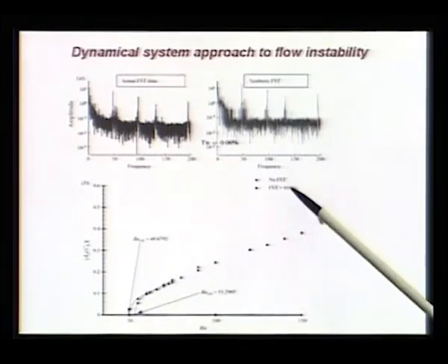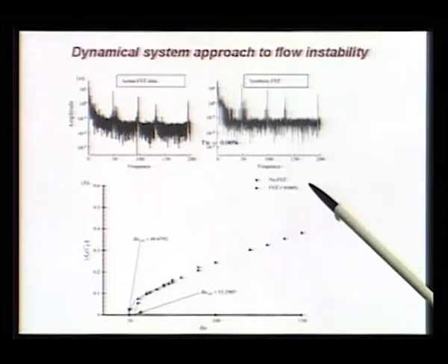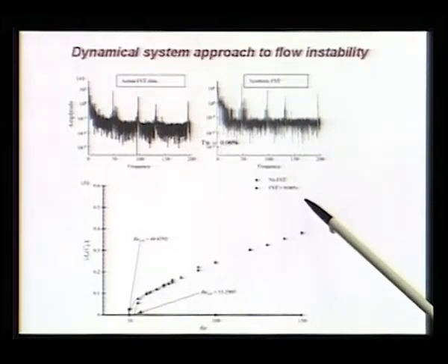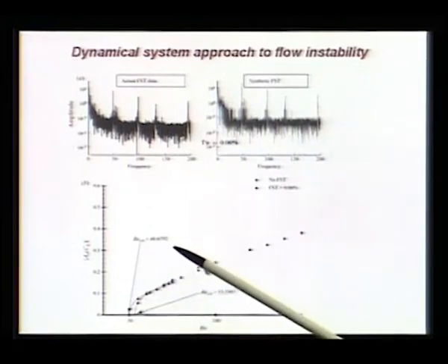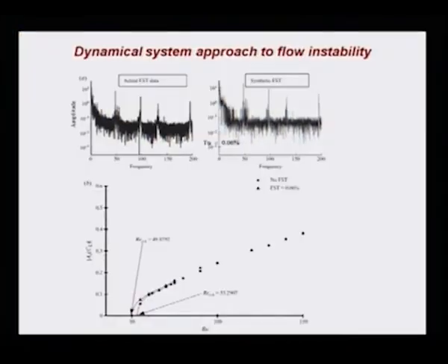The moment we switch on an FST model with 0.06% Tu, we get a value of 49. So, this is what people should actually be doing, and we have successfully demonstrated here that indeed the background disturbances can create a Hopf bifurcation onset at an earlier Reynolds number.